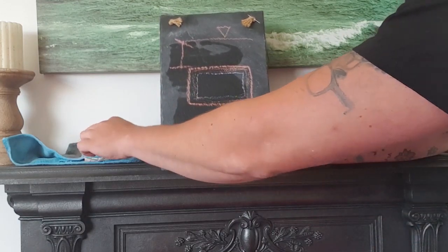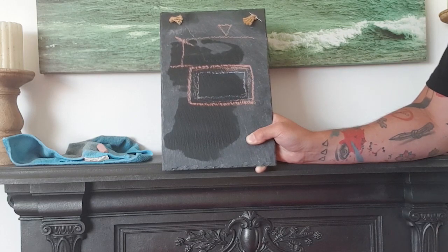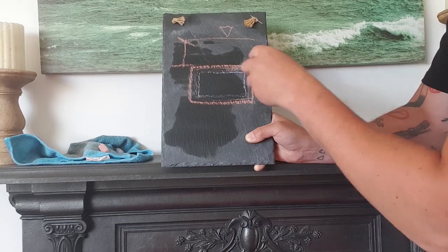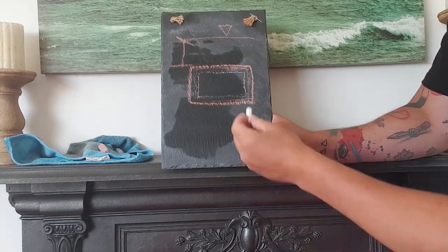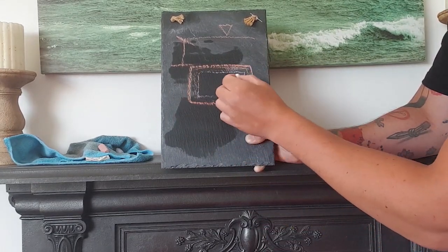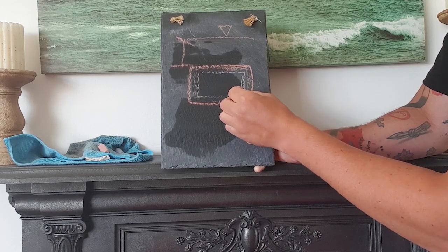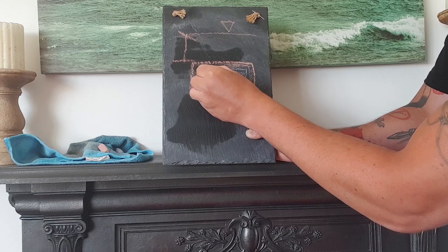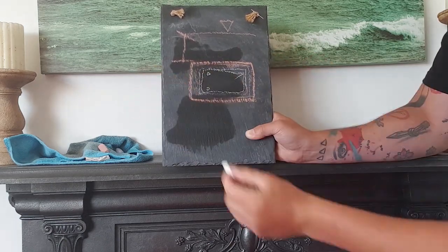And that's to stop corrosion for the rebar. The rebar will swell and it's to stop exploding of the concrete. And then inside the cover is where you're allowed to place your rebar. And in this cover, you will have perhaps links, like so, and straight bars that go that way.